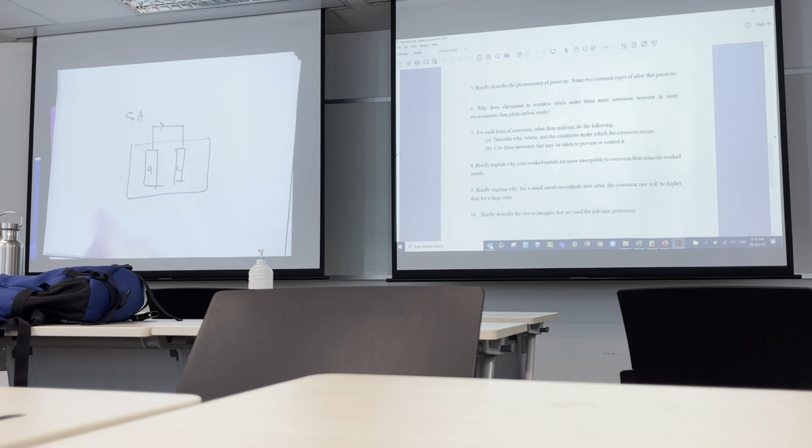Using a material. Actually, another way of doing things is, for example, some of the big structures, what they have done is they don't do this. They create a power supply to actually drive current here. So they use basically electrical power to create a current, so that it flows this way. So this will be the cathode, over here will be an inert electrode. Okay, this one will not need replacing, but you need to actually turn the power on. So this technique is called impressed current. So you're actually pumping current over here to protect the structure.